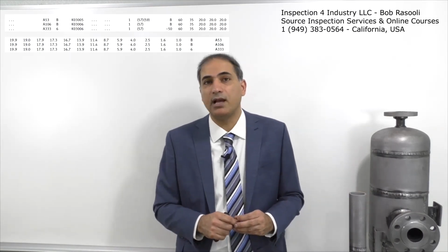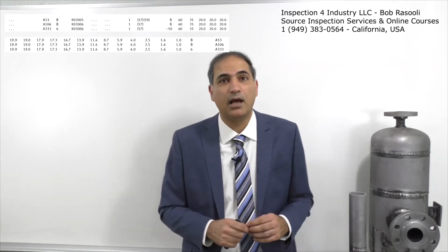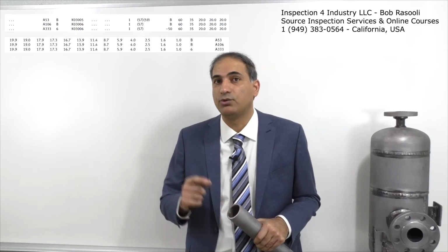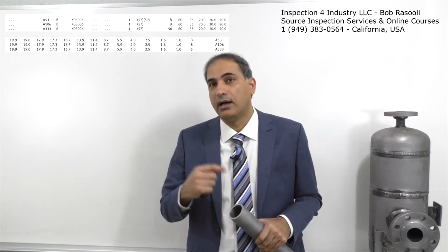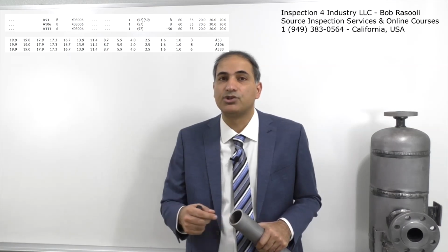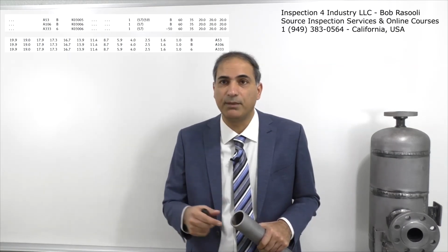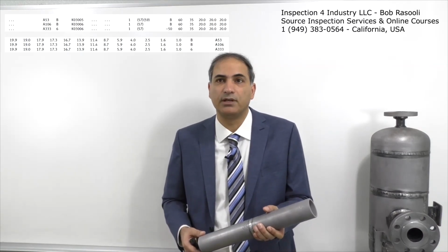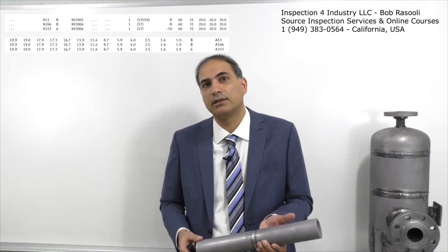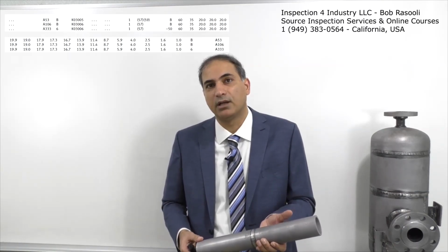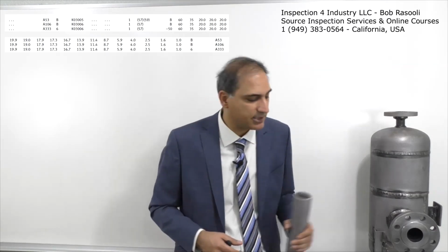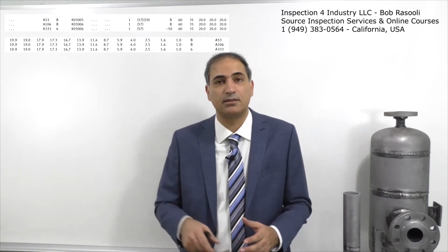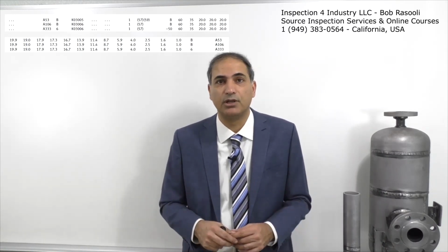That depends on your design temperature. You're going to read that allowable stress at the design temperature. Like I said, 35,000 psi is your yield point, and 60,000 psi is your tensile strength at room temperature. What if I put this in a furnace and raise the temperature to 600 degrees Fahrenheit, or to 1100 degrees Fahrenheit, and then put it in a tensile machine? We have a tensile machine that can make all of these tests, yield, strength, tensile and elongation at elevated temperature.